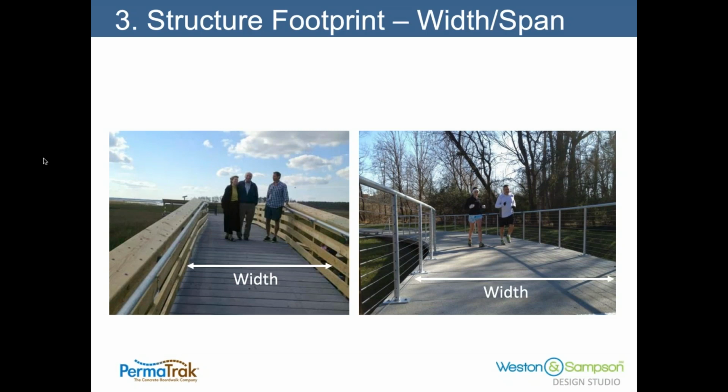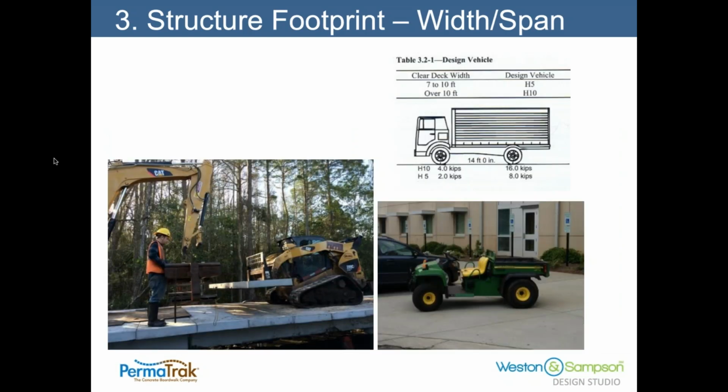And I would say most designers or owners are designing towards maybe a 10 or a 12 and even 14-foot clearances now. There are definitely places in the country where we've been asked to design a boardwalk that is 14 feet wide, and the reason being is they want to run heavier vehicles, potentially emergency vehicles, ambulances on it. Sometimes the construction process drives how wide the boardwalk is. Not very often, but sometimes it will. But those are things to think about when you're trying to decide how wide the boardwalk needs to be.